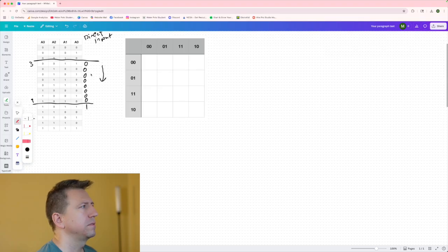And so let's assume that we're not going to have any other states, and we're just going to be counting up through these states that we start at 3, and we're going to count up through these states, and then we're going to reach the number 10, and then it's going to go back to the number 3. In that case, we have don't care conditions for all the other states.